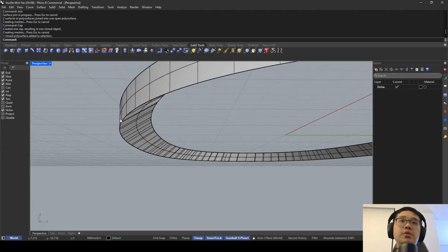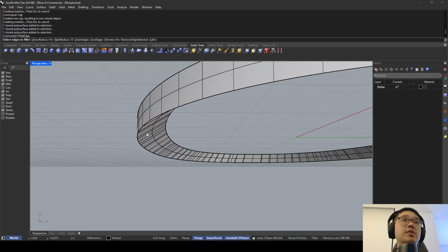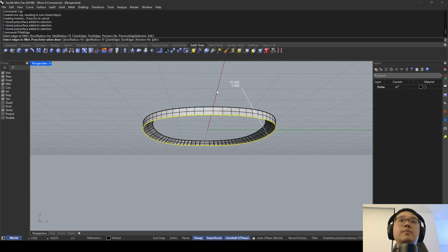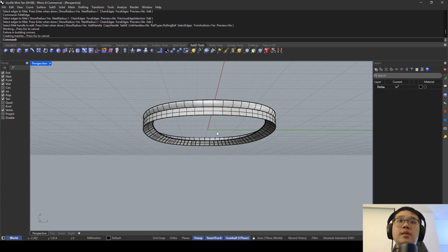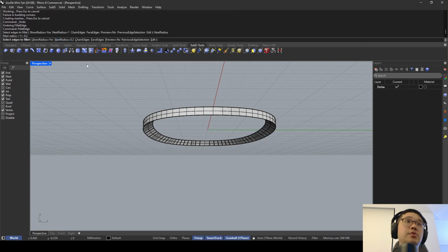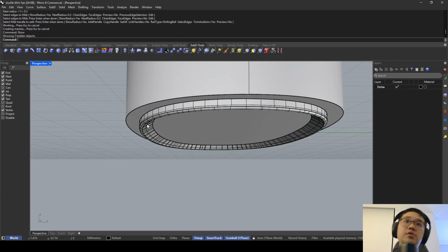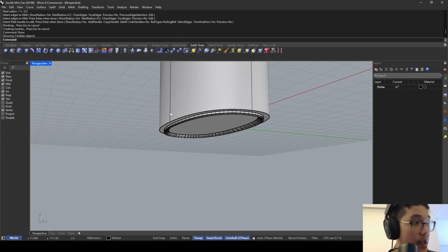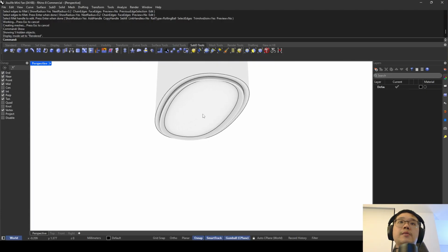And the next one here is to fillet off the corner here, because nothing's going to be this sharp in real life. So I'll just fillet edge, select the edge here, change this to about 1 mil. It's going to be really small. 1 mil is too big actually. 0.2. Let's try that. Yeah. Command show. And this looks good. I'm happy with this.